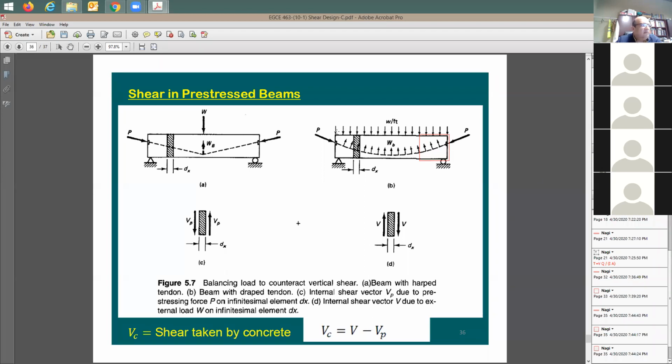Same thing here. The section that you're going to see, maybe in some designs, you're going to see some cracks and pre-stress is going to be maybe this section here. And the good thing about this section, this is going to be the section with high shear forces, because the shear force is going to be high here, it's going to be high here, it's going to be almost equal to 0 at the middle. So actually this pre-stress is going to be helping me with Vc. I said, okay, good. What else?